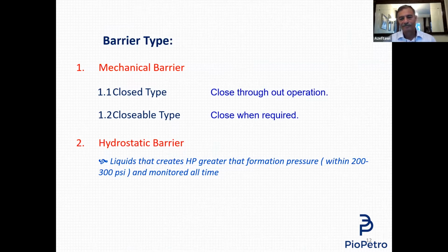Monitor it all the time. If you are using a fluid as a barrier and it creates hydrostatic pressure greater than formation pressure within a reasonable amount, and you cannot monitor it, it is not a barrier. That's why during drilling, the mud engineer normally takes samples from this drilling fluid to be sure that its density is within the design density. Otherwise, it is not a barrier.